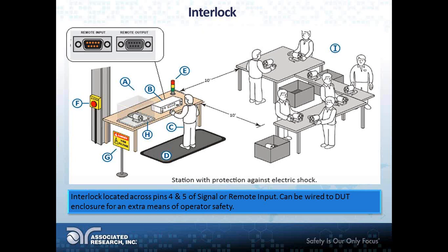I know there's a lot of customers that don't realize this because I get calls, and I answer the phone. My unit's not working. My first question, 100% of the time, is your interlock back there? Because 50% of the time, in fact, it was not. So you do have to have that in there, or you can wire it up like you see in this safe operator setup here. So another great safety feature to take advantage of if you can.